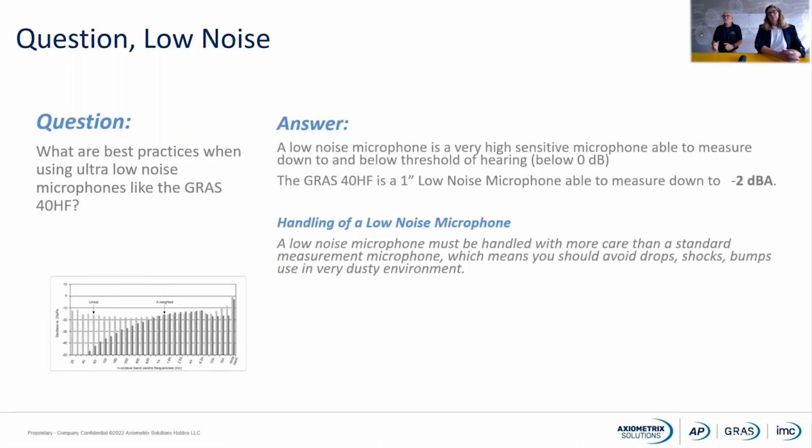Handling of a low noise microphone. See, a low noise microphone is a little bit more sensitive than a standard measurement microphone. So a low noise microphone must be handled with care. It means you should avoid drops, shocks, dumps, and it should not be used in a very dusty environment.